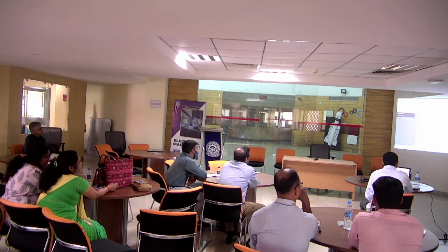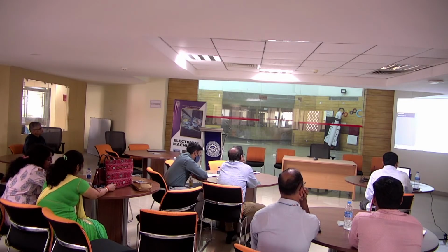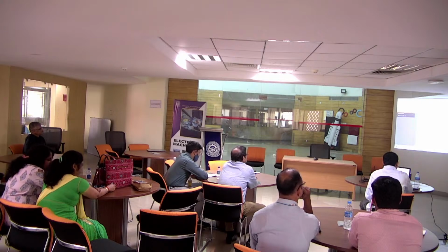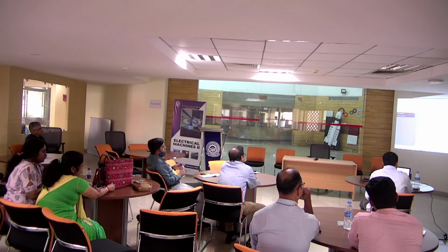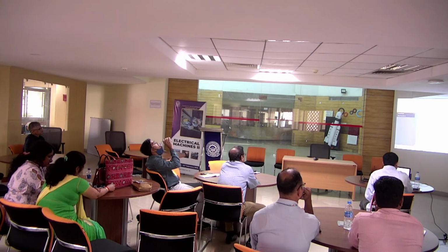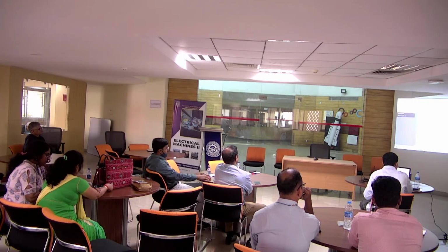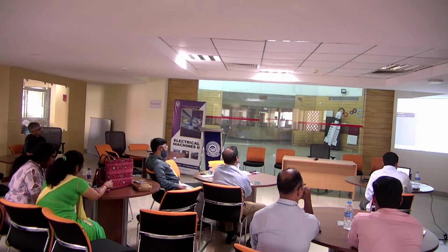Now what to do? Apply some load to the motor. An indirect load, a DC generator, he has taken. Simple way. Okay, some load is applied and the values are noted down. Now what should we observe? We should observe the change of armature current with respect to the field current, and the power factor also simultaneously, so that we get to know the range at which we can operate this synchronous motor, and how the maximum power factor practically varies at the minimum armature current. We tested this for one load now.